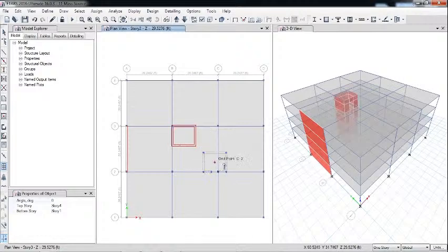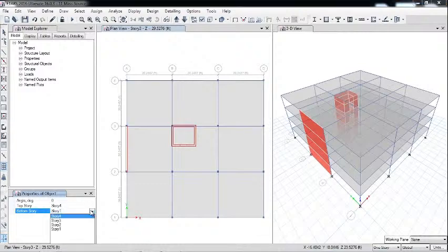Here I have selected the shear wall, and the shear wall is automatically drawn in all the stories from top to bottom because it acts as a lift. So here is the setting. If you want to make the wall only from story 3 to 4, then you can select up to your requirement. Because I have just selected it as a lift well or lift wall for the building, that's why its setting is from top to bottom.